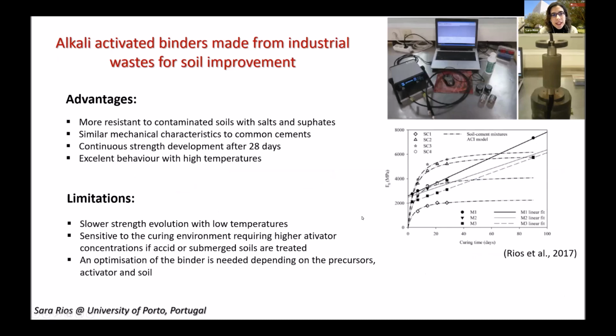I've tried to summarize here the advantages and limitations that we have found on these binders. For example, we tested these binders with contaminated soils and with saline environment, very harsh conditions. And we found out that a saline environment, which can be not so good for Portland cement, is in fact beneficial for an alkali activated binder, because the saline water generally has higher pH than distilled water. So that can be a good option.